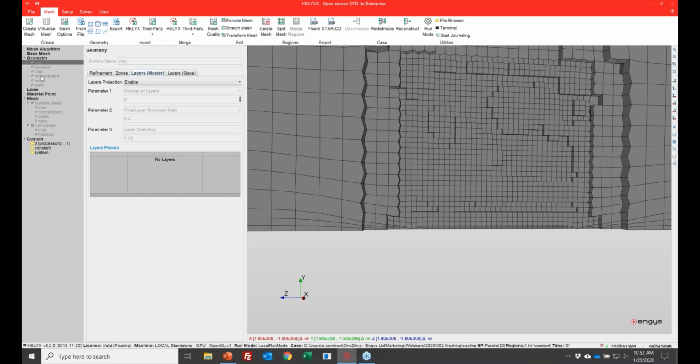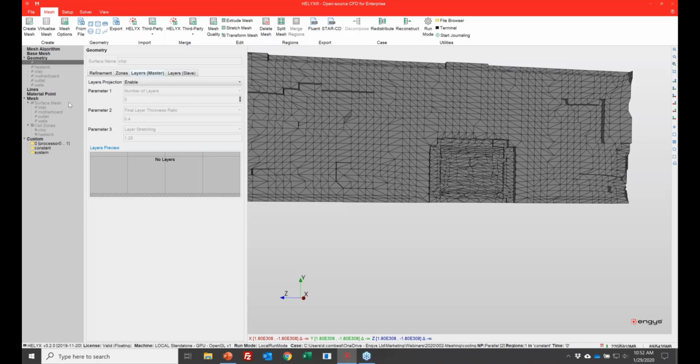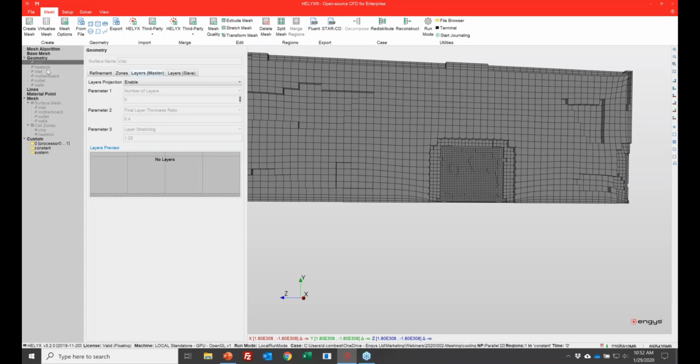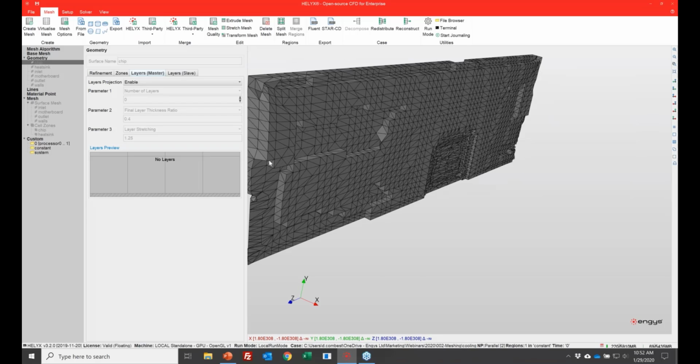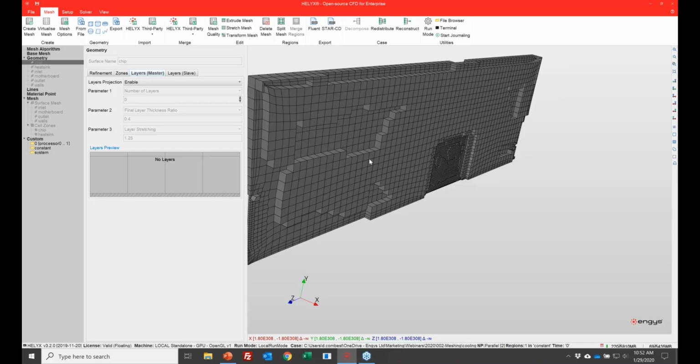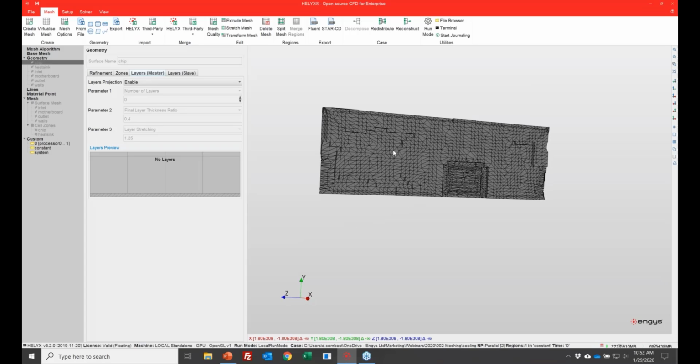All right, great. So chip. We've enabled snapping to get rid of the issue of the inlets and outlets not being resolved as much as we like. We could get around that by also increasing the resolution of the surface refinement, but I don't want to add more cells unnecessarily. I'd rather resolve it another way to keep my cell count low. Another thing is we wanted layers to grow on the inlet and outlet, and we also wanted to prevent layer collapse where this chip cell zone is. Now, finally, one last thing.